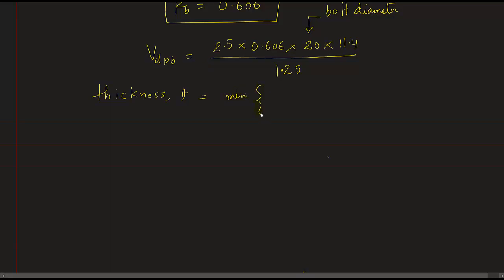So we have to consider the flange thickness of ISWB 350, that is the section of this column. This thickness value we can find in SP6.